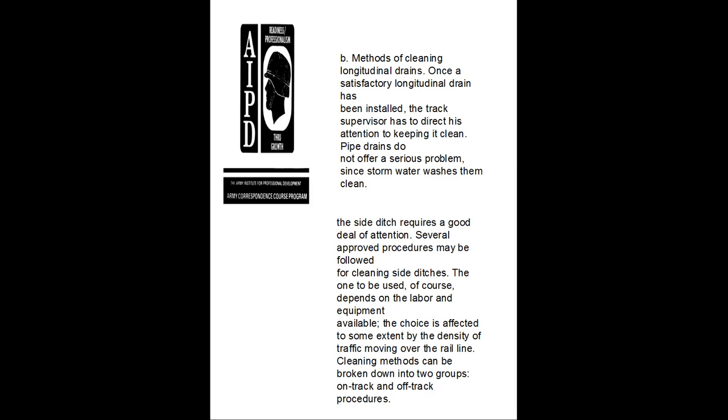The method of cleaning longitudinal drains is satisfactory. Once a satisfactory longitudinal drain has been installed, the track supervisor has to direct his attention to keeping it clean. The pipe drains do not offer serious problems, since the storm water washes them clean.